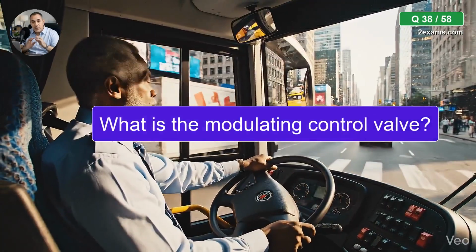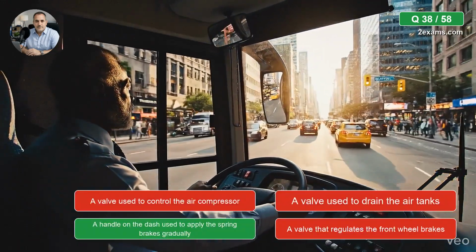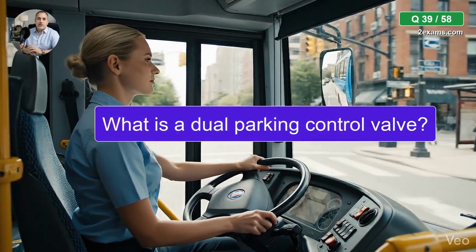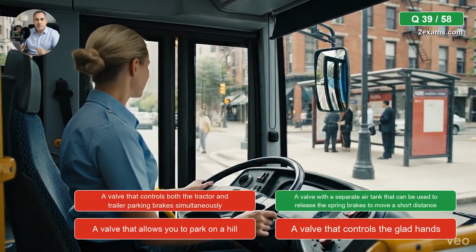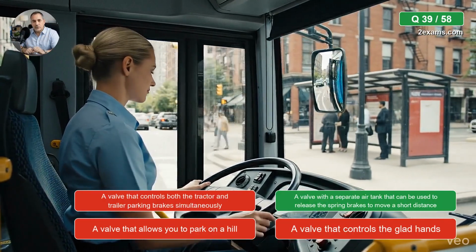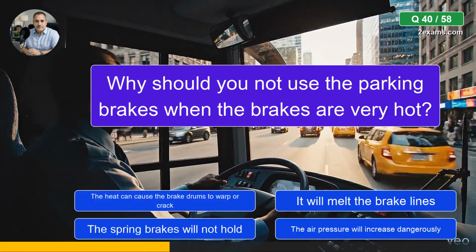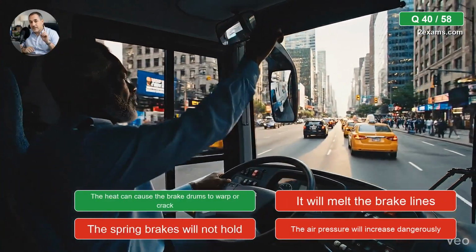What is the modulating control valve? The correct answer is, a handle on the dash used to apply the spring brakes gradually. What is a dual parking control valve? The correct answer is, a valve with a separate air tank that can be used to release the spring brakes to move a short distance. Why should you not use the parking brakes when the brakes are very hot? The correct answer is, the heat can cause the brake drums to warp or crack.